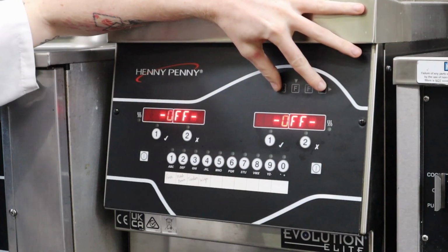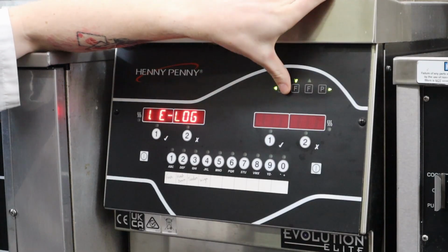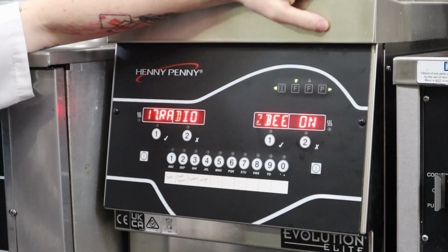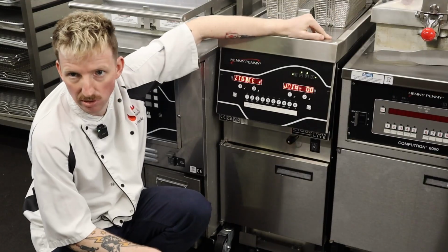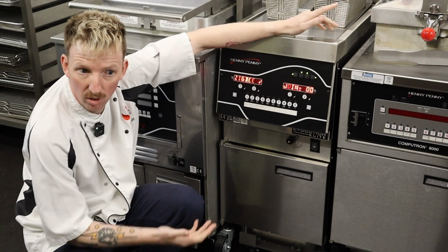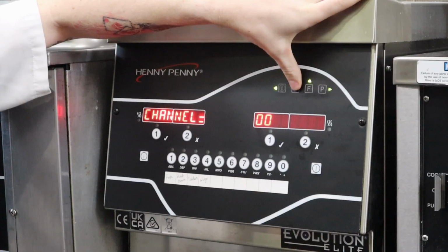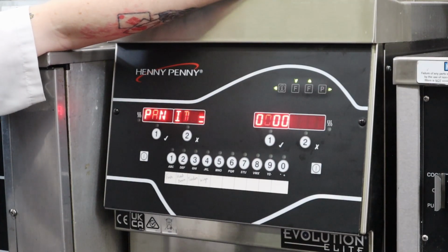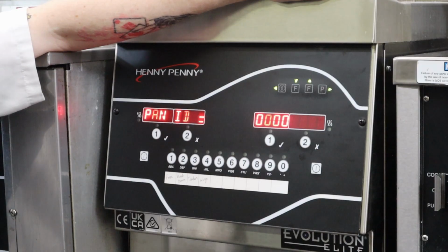Now we go back into our info mode, back over to our radio panel. That reset will now have taken place, and if everything's working fine, that join sequence should have started up. Now we're getting zeros here on the screen, which is different to our velocity where we were getting Fs. Now the Fs mean we've got a radio talking to the controller and it's just waiting for that information to feed through.